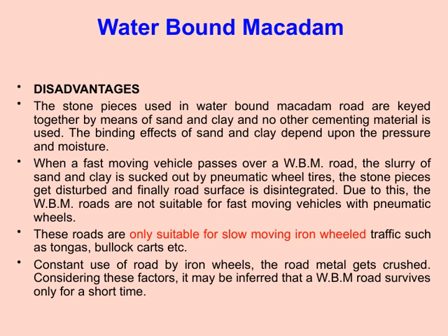Another critical point is how these roads perform under the weight of fast-moving vehicles. When a vehicle travels quickly over a WBM road, the slurry of sand and clay can get sucked out by pneumatic tires, which are common on modern vehicles. This process disturbs the stone pieces, causing the surface to disintegrate over time. As a result, WBM roads are generally not suitable for high-speed vehicles with pneumatic tires.